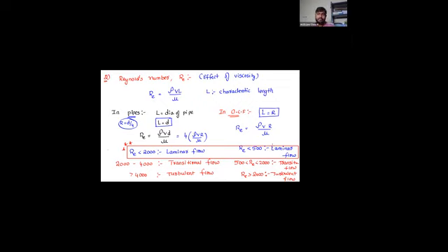And in soils, whenever there is a flow in soil, there RE less than 1 is known as a laminar flow. And in the case of environmental engineering, I hope you came across the sedimentation analysis. There you came across the Stokes law. In Stokes law, again there is Reynolds number. There RE less than 1. So the type of medium changes, and for laminar flow, the Reynolds number also changes. Okay. So that's all for today.